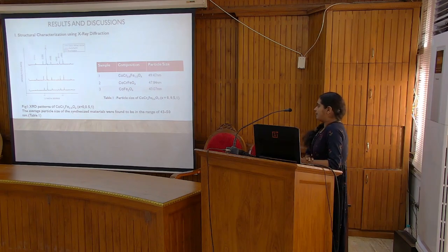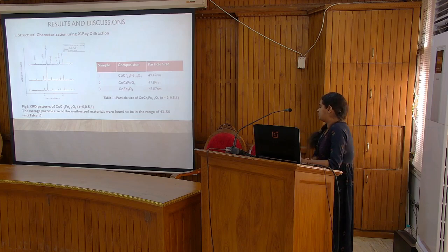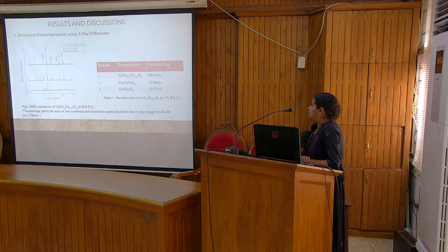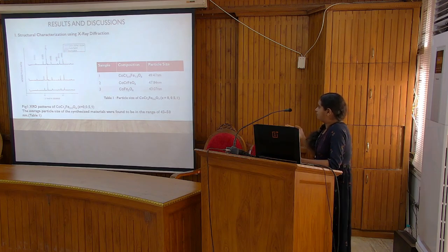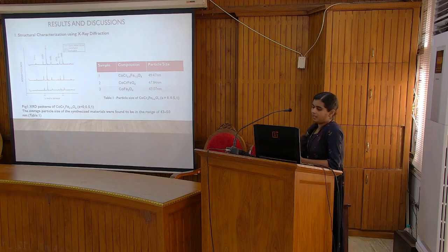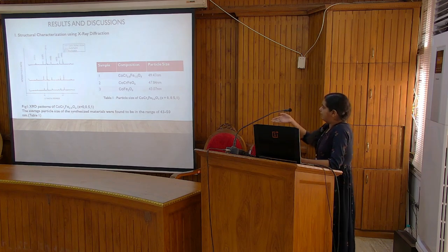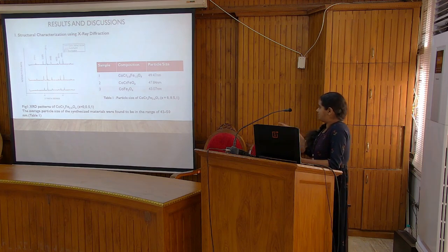The XRD patterns obtained were compared with the ICDD data, and it confirmed the presence of the synthesized material, and all the peaks index to the spinel structure. The particle size for the various chromium doping concentrations is given in Table 1.